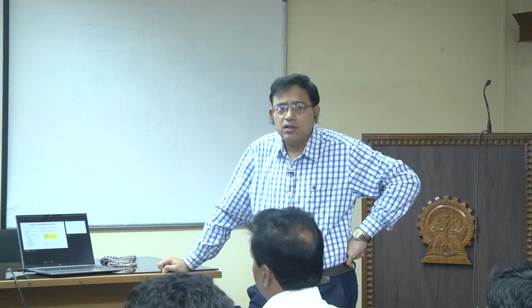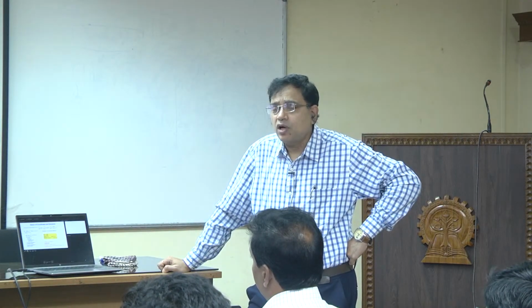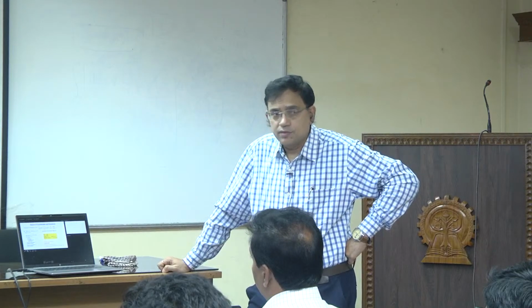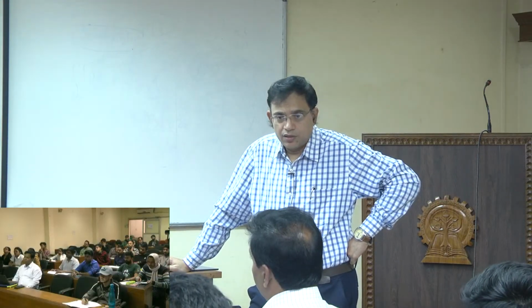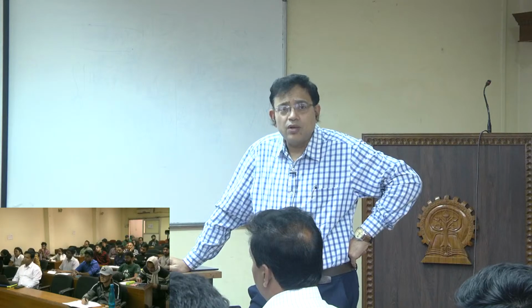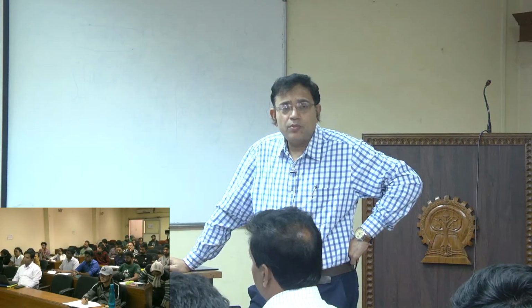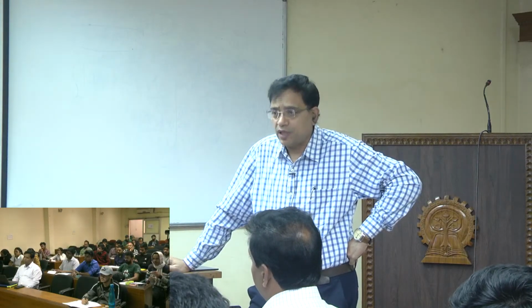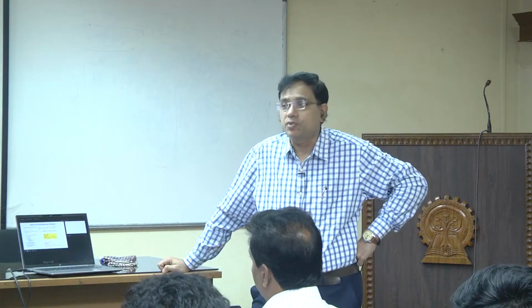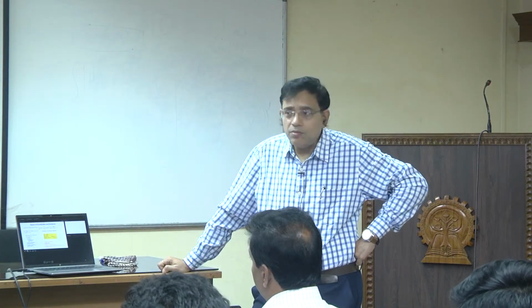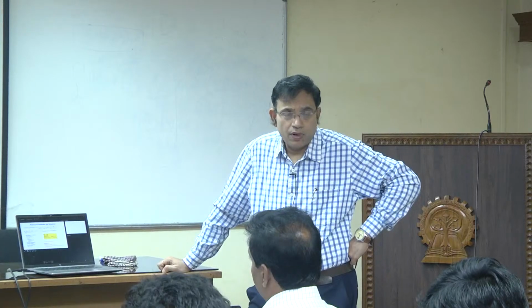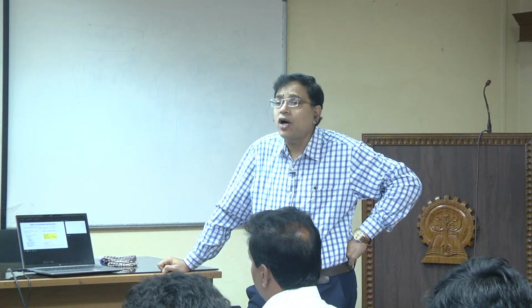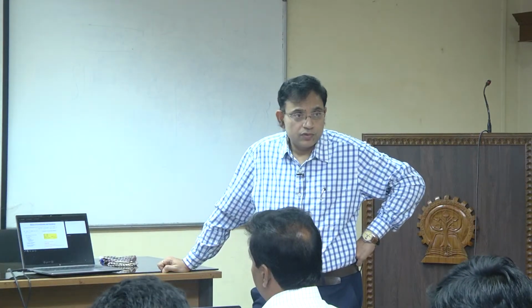We cannot influence what was the temperature 1 hour back, right. So, whatever was 1 hour back was 1 hour back. We can influence only what is going to happen from now till in the forward of time. So, this is called a time marching problem. So, this time marching problem is technically a parabolic problem. So, that means you have a one way coordinate system.